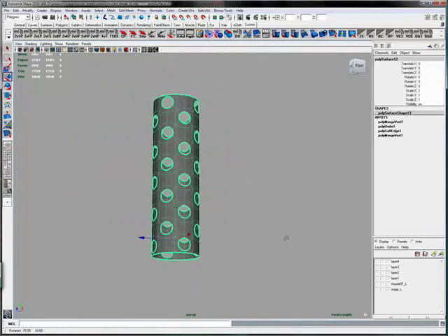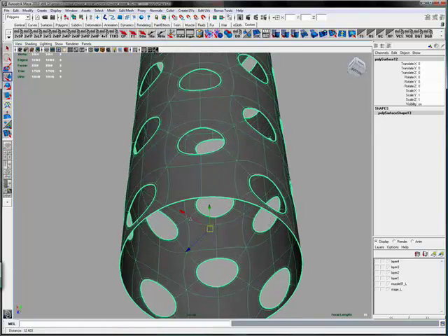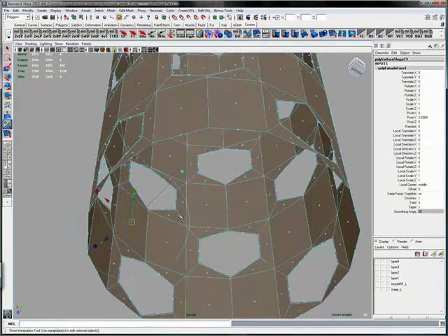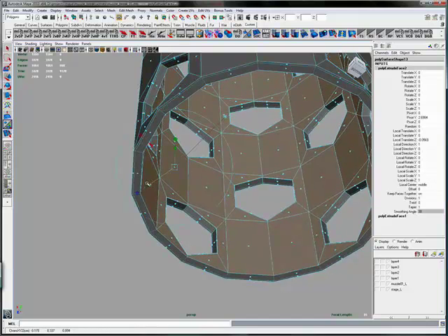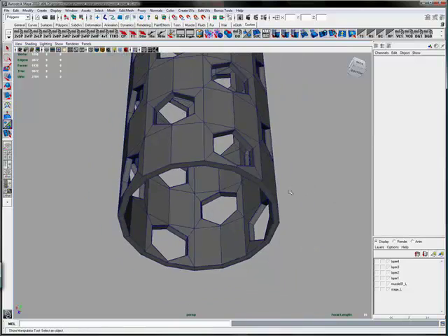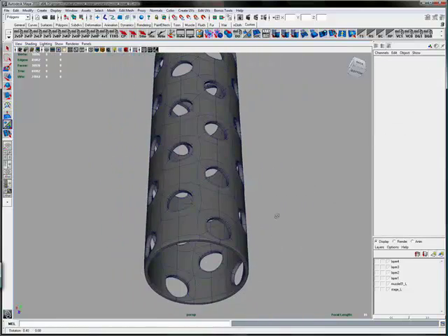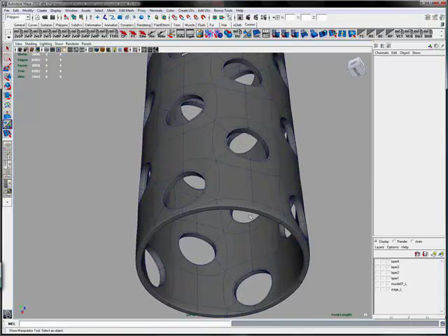Now what we need to do is add a barrel. Alright, we have to add some thickness, so what we'll do is select the whole object, scale it in a little bit, scale it for some thickness, and then scale it one more time. What we're doing here is creating 3 edges so that we get tight edges around the ends of the cylinder there.